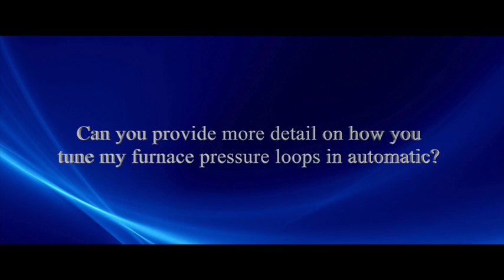Ideally what they call quarter amplitude, where each successive peak is 1/4 of the last one. Then you get a period, and that period is going to be larger than the ultimate period. But all that does is give you a more conservative reset time, which I think is good. So you're going to end up with a conservative reset time because the actual period you're measuring is much slower than the ultimate period.